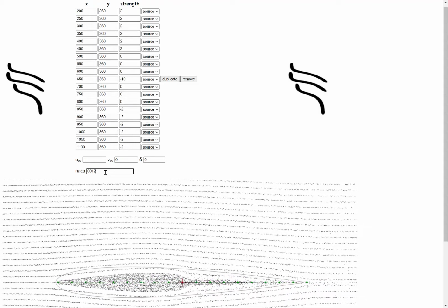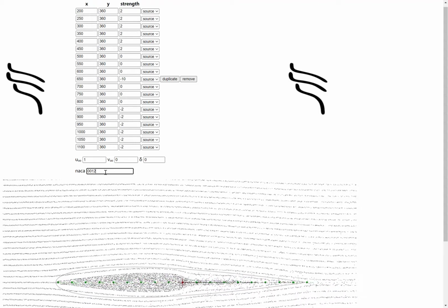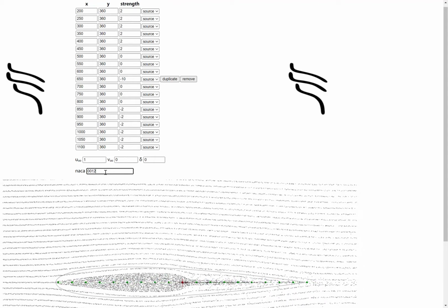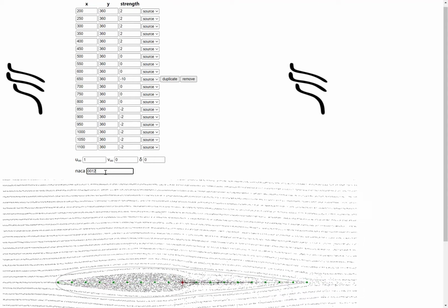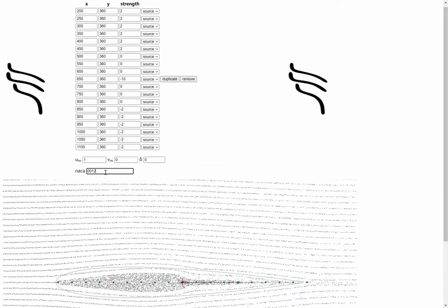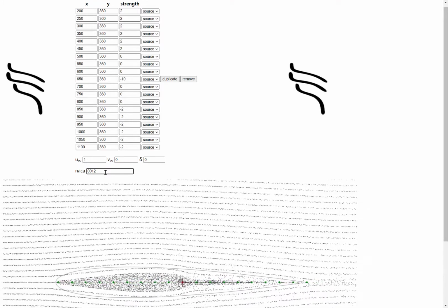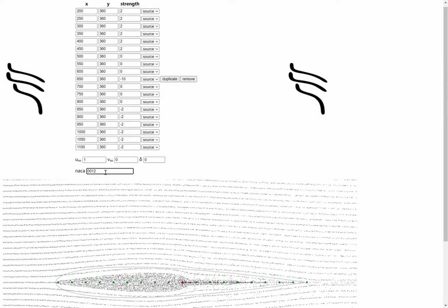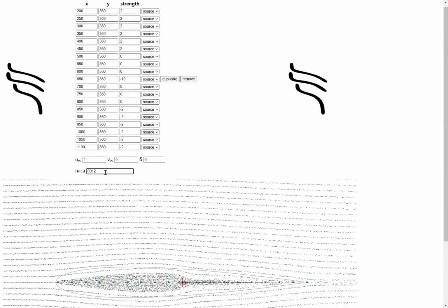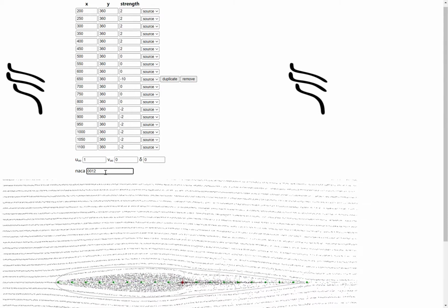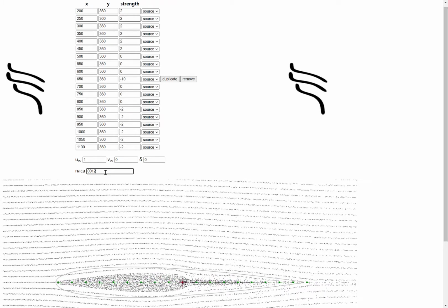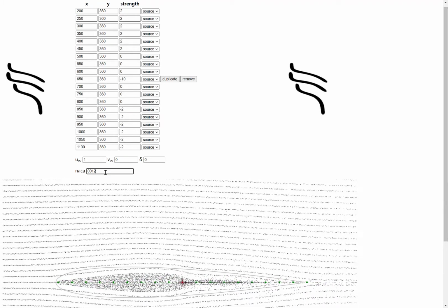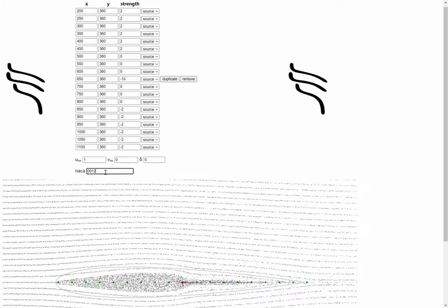Keep all the locations except for the first one. You are free to move the first source a little bit in the streamwise direction, upstream or downstream, but keep the location of the other sources exactly where they are, and only change their strengths, so that the flow goes tangential to the entire NACA 0012 airfoil.